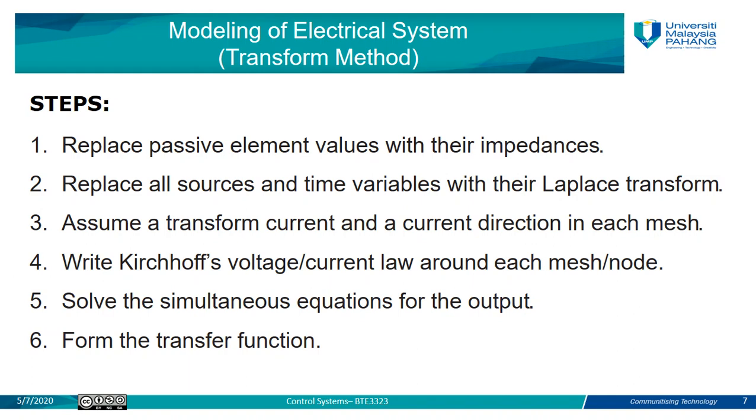So you solve only for the variable that you want to know. I mean, you are not going to solve for all variables. If I want the value of I2, I solve only for I2, or the equation related to I2 only. After we solve the equations, we can find the relation between the input and output of our electric circuit. From this relation, we can find the transfer function of our circuit.